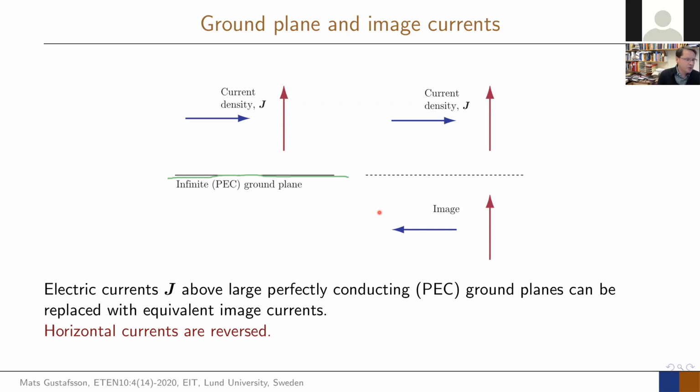But if you have, for example, a metallic part of a car or a boat or something, that typically works like a ground plane. And as long as this is fairly large compared to your antenna, you can treat it as this infinite one, at least in the first approximation, which gives you quite a lot of understanding. And in many cases, we can even treat the ground in the first approximation as a good big ground plane. So it gives a very easy way of doing things.